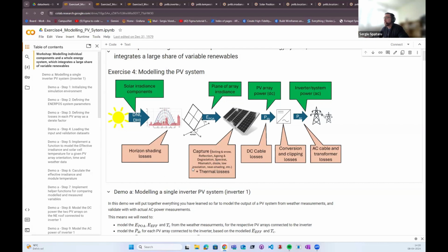because they have a voltage loss as well. Some of the older panels used to have lower efficiency at lower insolation, and also as panels degrade, especially through PID or shunting type degradation modes, their efficiency might no longer be constant. So they might have one efficiency at high irradiance and another one at lower irradiance.